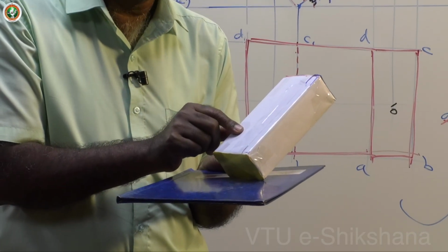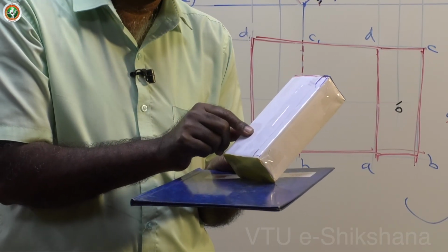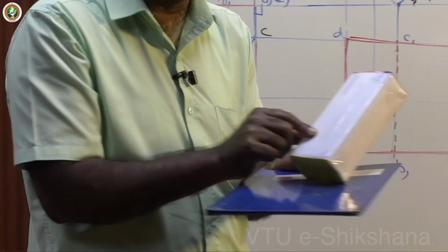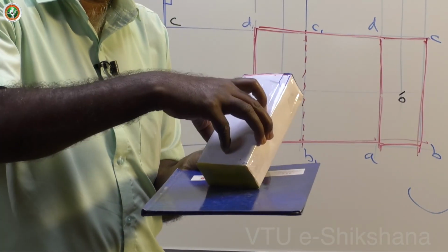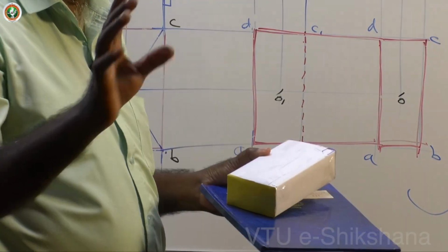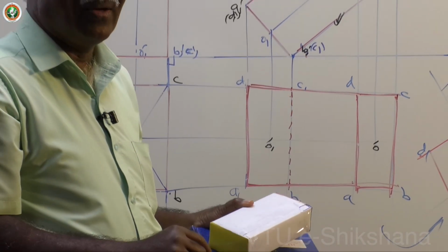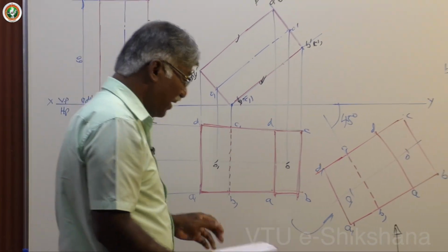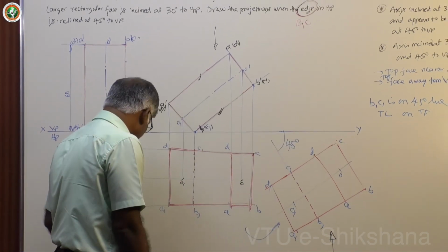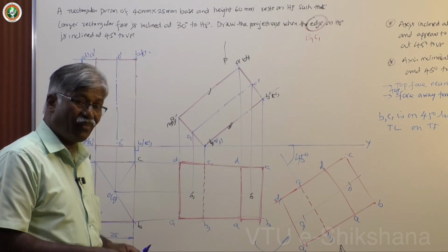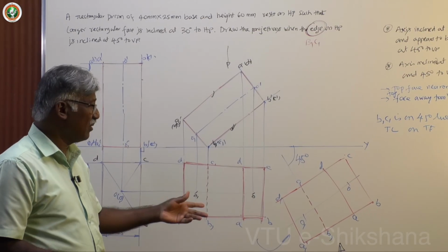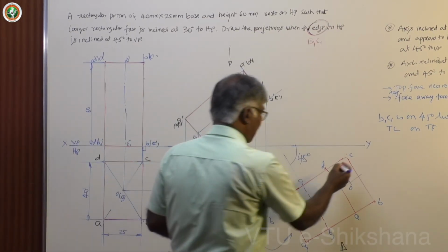Yellow color base surface is visible. Red color top face is away from the observer, is not visible. It's very clear. First, second position, third position. So, base is visible. That is the only criteria I need to complete the final front view. So, first let me draw the projection with light lines. Even if you use either farthest point method, or the key surface method.